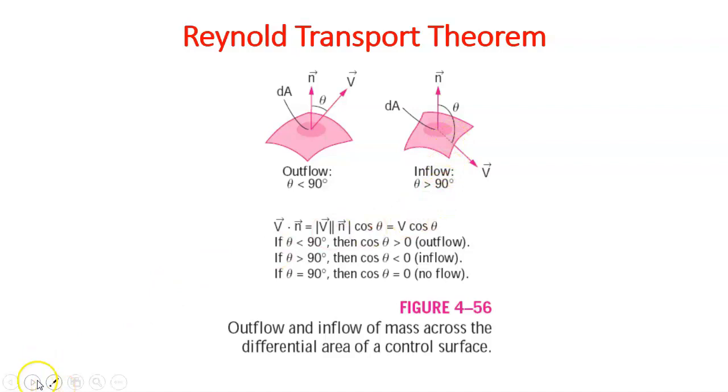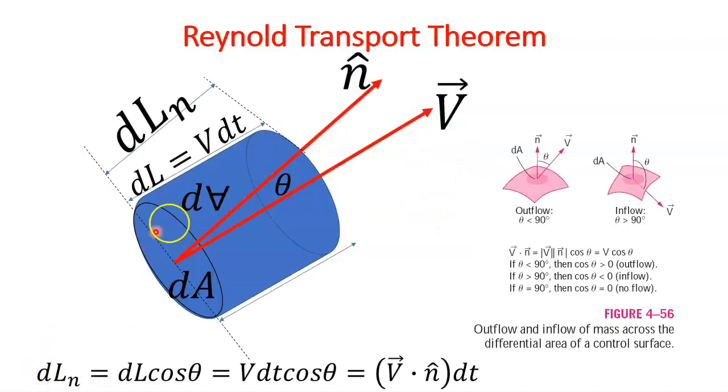So with this idea, we shall consider this is the area dA and the flux is leaving through this area with velocity v bar in this direction, and let us suppose that n cap is a vector normal to this surface. Now in time dt with velocity v, the matter will advance a distance v into dt, which we are representing as dl length.